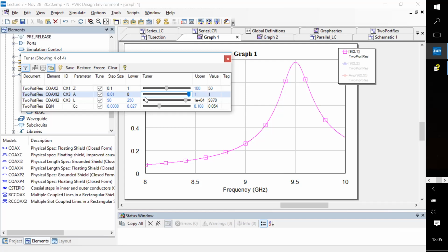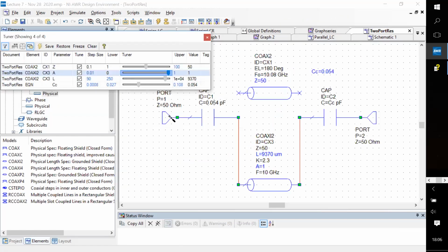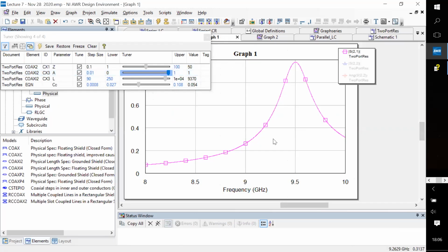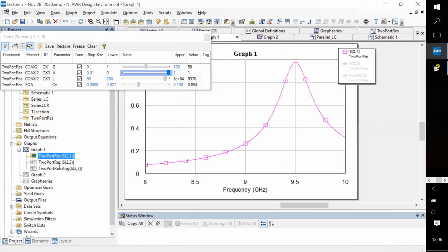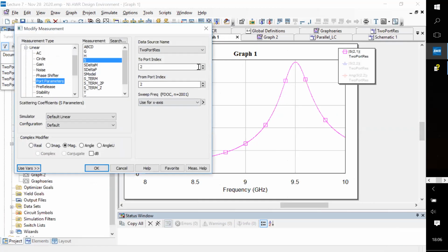Okay. So this is as expected, as I said, because of conservation of energy. Remember that it is always with respect to the input port. So all of these quantities are with respect to how much power is being sent here. So if there is some absorption here, you cannot get unit transmission on the other side. However, there's something even more subtle here. I think it should show up here. I'm going to enable the reflection measurement from port 1 as well.